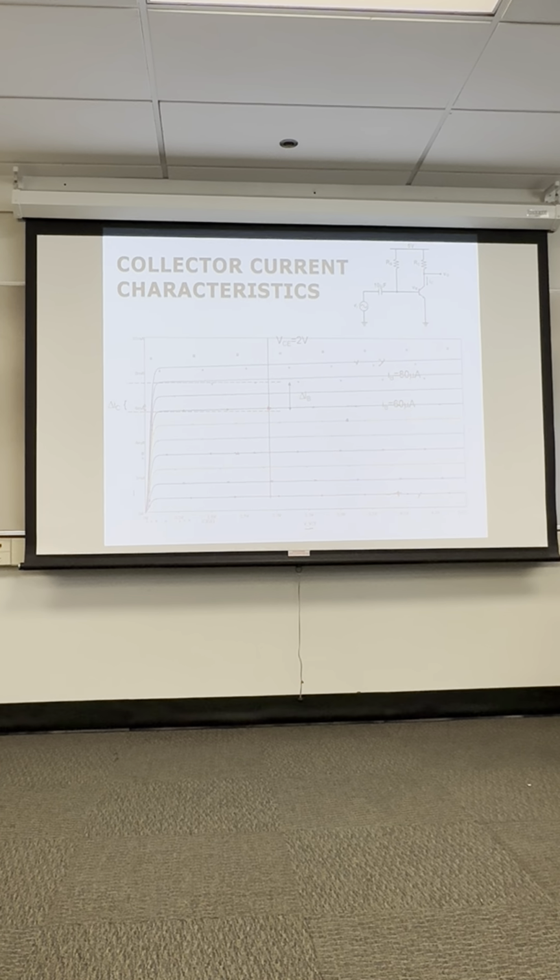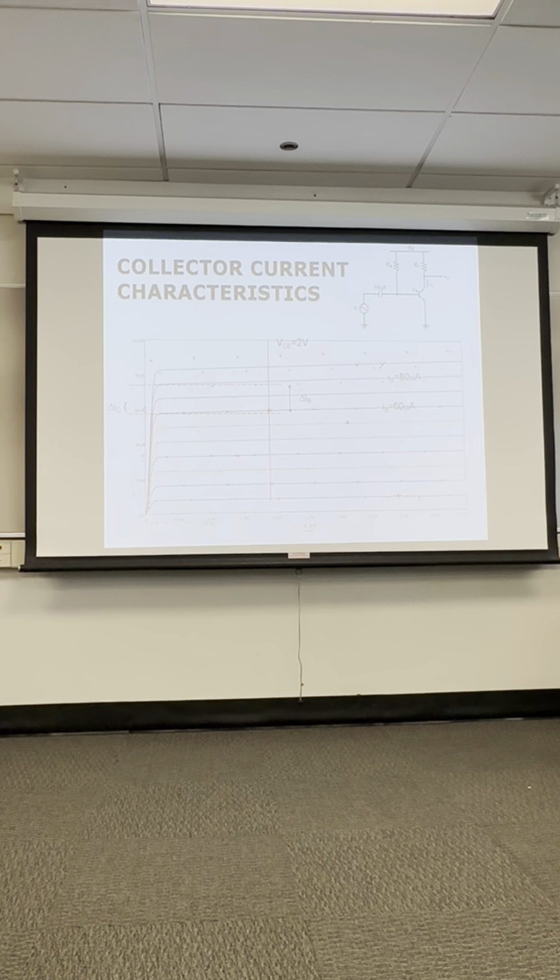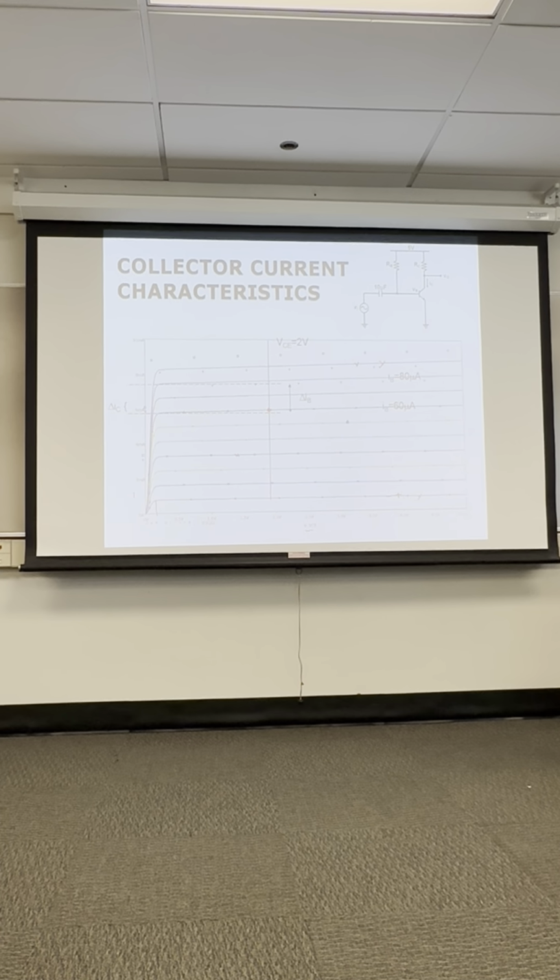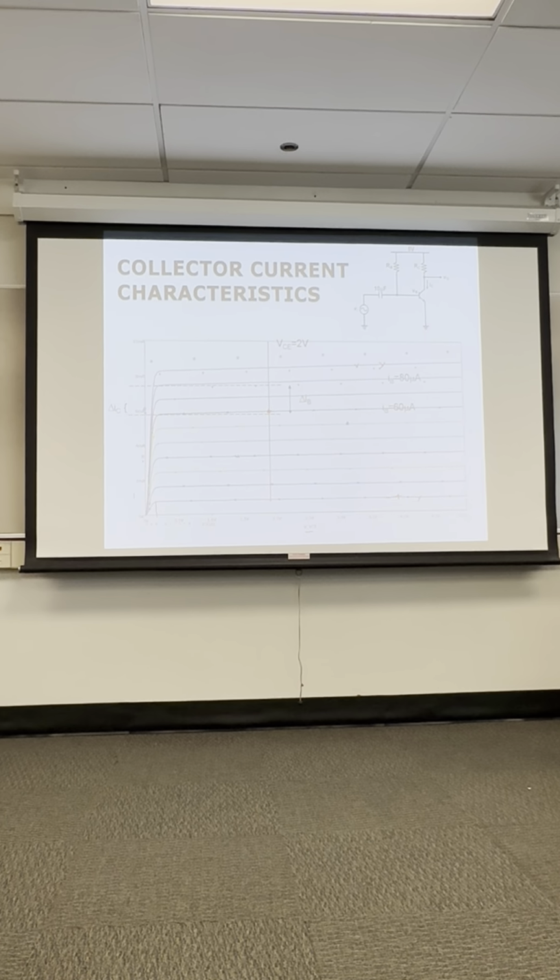And then, in terms of collector emitter voltage, we avoid this point over here, very low VCE. This is actually where the transistor moves into saturation. When the collector emitter voltage gets to be around 0.1 to 0.2, what happens is the collector current abruptly starts to drop.